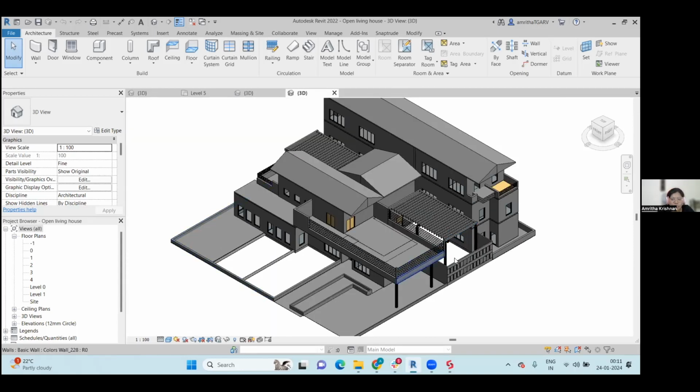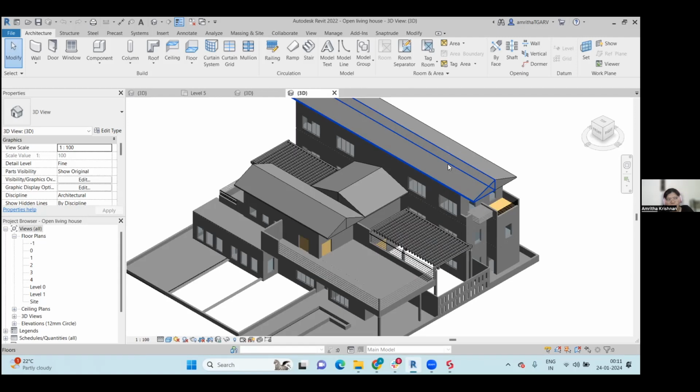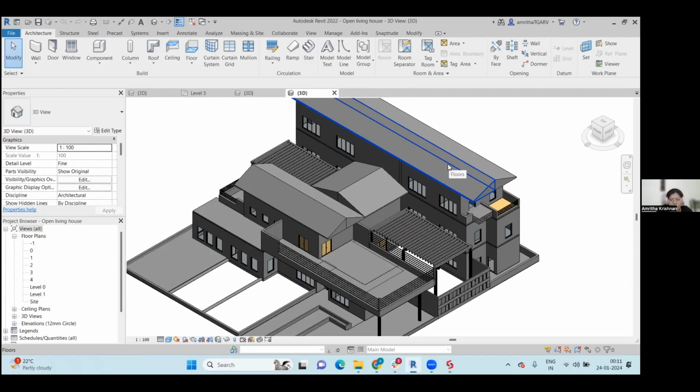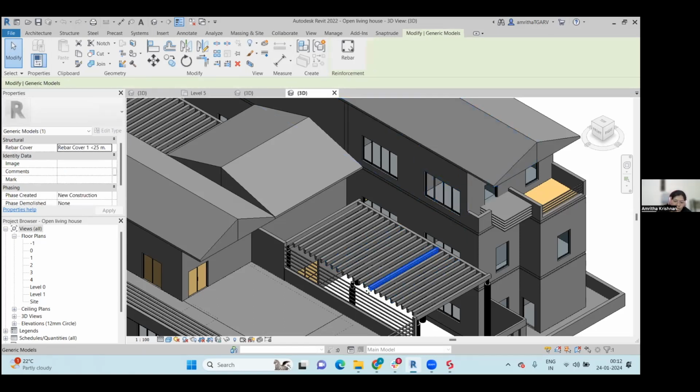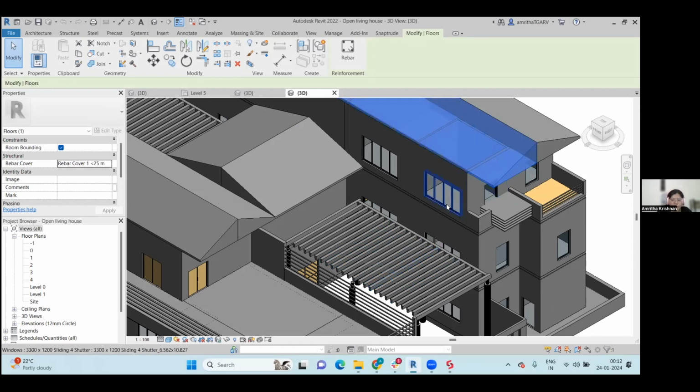The fidelity of the Revit export at this point is 100%. All of your elements get recreated, but not 100% of them get recreated parametrically. That is the caveat. The strength is that most of the objects that are recreatable on Revit, which is the walls and the slabs, doors, windows, floors, beams, columns, all of these objects get recreated. The ones that are a little bit tricky are things like pergolas, railings, and sloping roofs. So these are not 100% parametric.